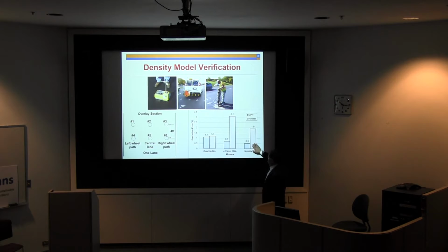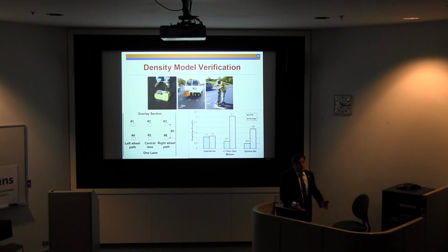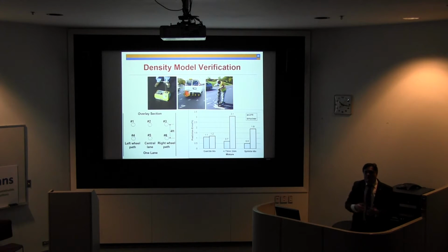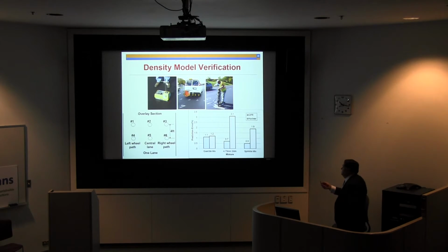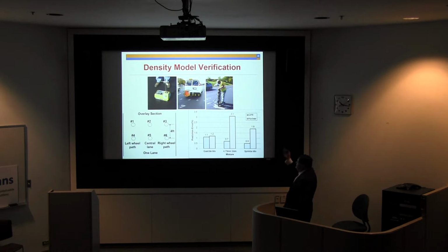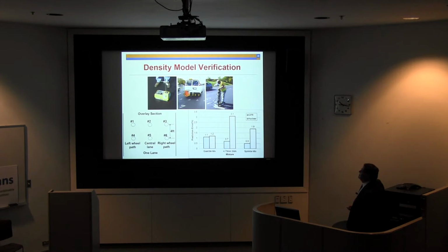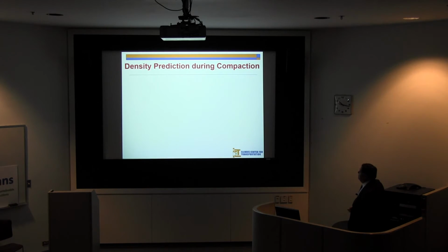This one, it was very clear here that the GPR was way much better, and the same for the sprinkle mix. So when things were a little different from the calibrations that you do for the nuclear gauge, then it will just go off. Okay? So the nuclear gauge depends on the calibrations that you do. Of course, 3% is still very good. I'm not saying that it's bad, but I'm saying here that this is a better approach.